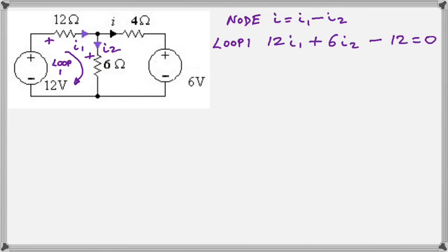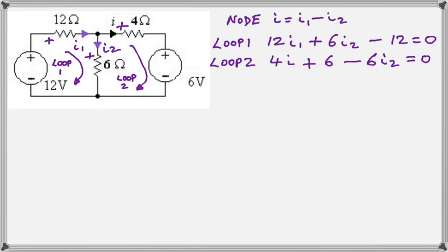But once you have put on the arrows, you then can label the plus side of your resistors. Based on the fact that the current is flowing into that end, it would have to be positive. So we've done that, and we've also written the equation for loop 1. So hopefully you're happy with that. If not, study it some more till you figure it out. And here is loop 2. And now we have all we need, and the rest is mathematics.